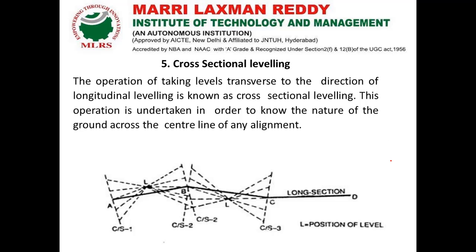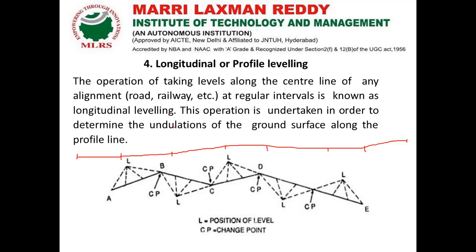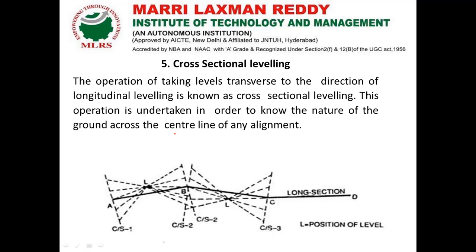And if I am going to take the readings widthwise, those readings are called cross sectioning. So whenever we are going for profile leveling, it consists of both longitudinal as well as cross sectional details together that we have to take.